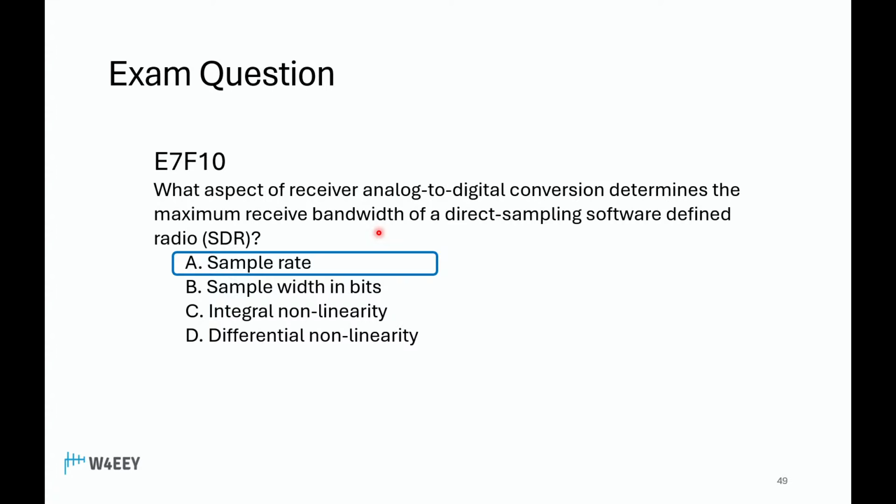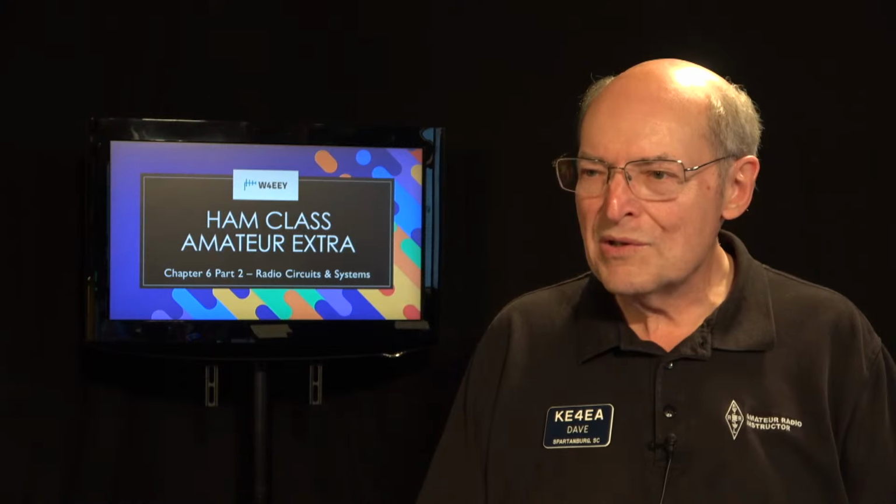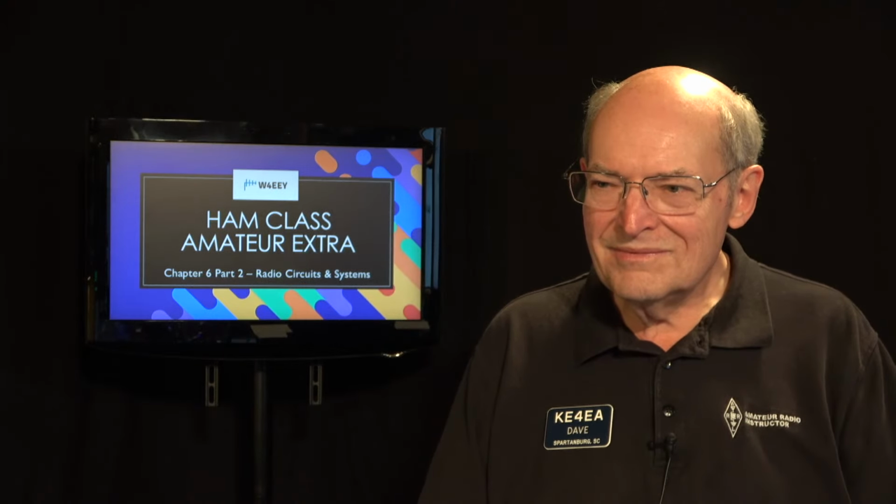You can see an entire ham band on a spectrum display, and the amount of signal that you can see is determined by the sample rate. And what's really amazing, just a brief sidebar here, it's possible to sample huge swaths of the spectrum. Your radio, the 6600, will it do multiple groups of frequencies at the same time, or the whole ham band? It'll do close to the whole ham band. I think it's about a 20 megahertz bandwidth. I don't remember exactly.